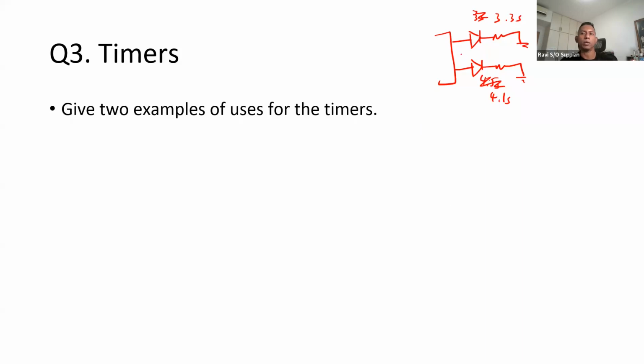Both of them have to keep on running at the same time, regardless of what other things are going on in your controller. The only way you can do something like this is to use some hardware-based solution, which is basically the timer. So I need to configure this to some timer 0, timer 1, or timer 2, and configure the registers to generate some signal that will drive these LEDs while I'm busy with the software. So the software can still carry on as it is in your code, but the hardware can control the LEDs.